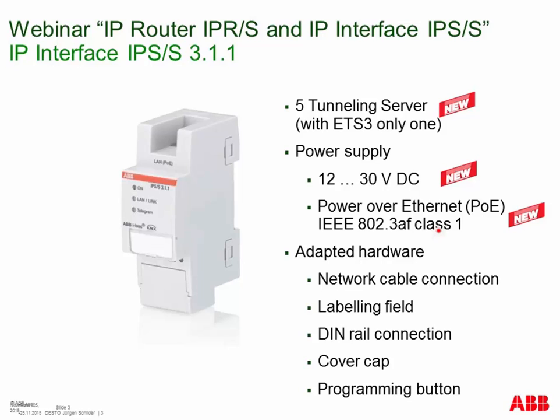Sometimes the question comes up why we have to use an external power supply. The very powerful processor inside this device needs more current than we can take directly from the KNX bus, so it's not possible, and that's the reason why we need an external power supply here.